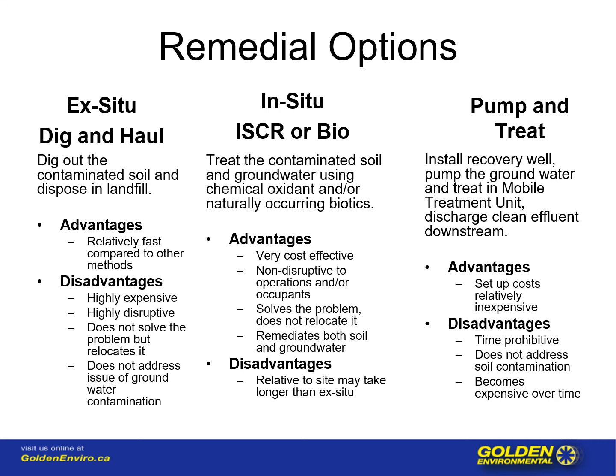One of the other issues that you need to look at when doing bioremediation is a sufficient level of oxygen. This is when you are using aerobic bioremediation. There are two types of microbes. They are aerobic and anaerobic. Aerobic microbes need oxygen in order to metabolize contaminants. Anaerobic do not use oxygen in order to metabolize the contaminant.